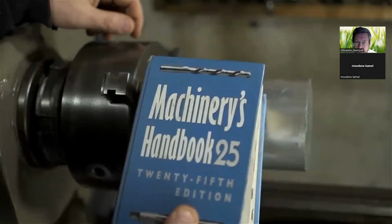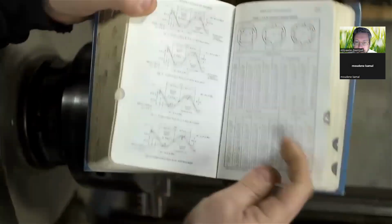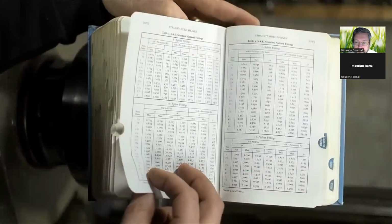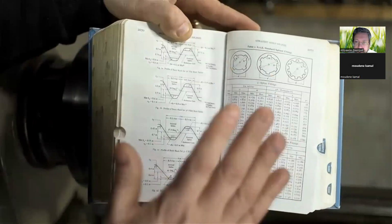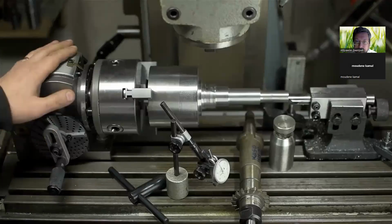First thing I had to do was find information on the 1-inch 6-spline PTO shaft. Of course, I turned to the Machinery's Handbook. Fortunately, this thing has all the information I'll need to pull this off. And since I'm only responsible for the actual spline, we'll knock this back down and take it over to the mill. You likely saw this coming, but I'm set up in the dividing head.